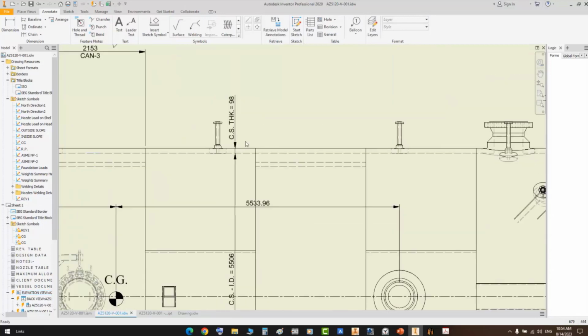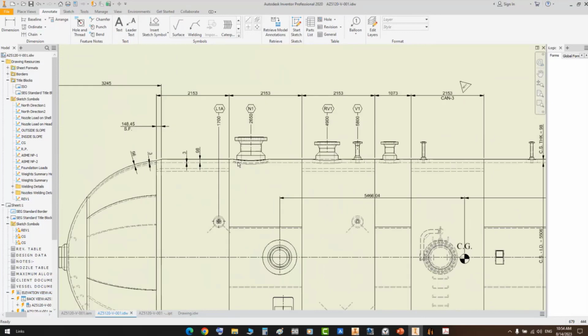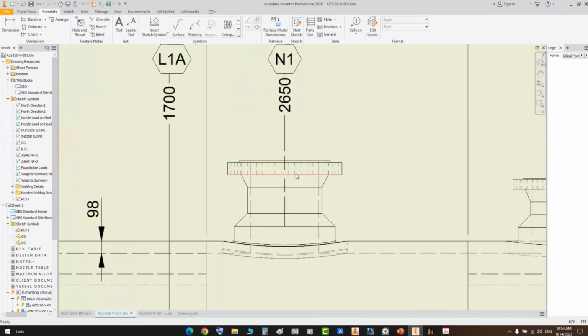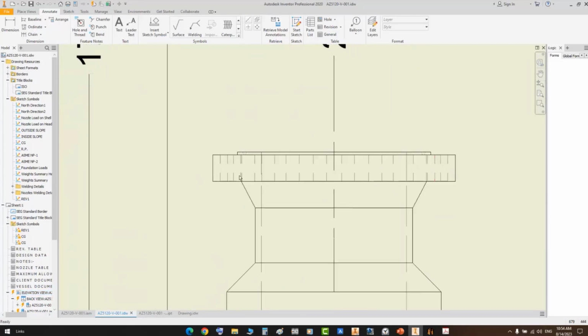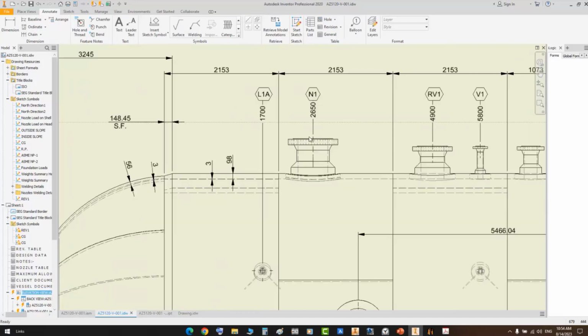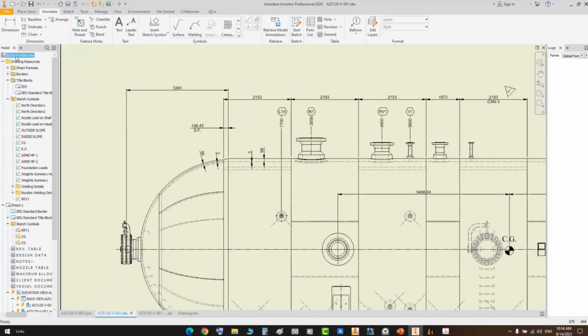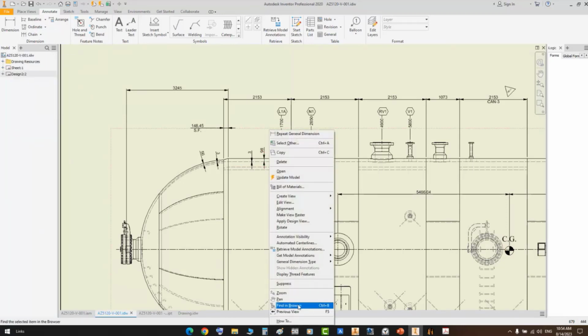Okay, that's fine. That's what I was looking for. One more thing I would like to indicate here. For example, for this flange, you may not want to add the hidden lines here. You can see that it's a huge number of lines, and I don't need it. So this item only you would like to make as a visible line only, not including any hidden lines. From the tree itself, if we collapse this tree, you can get this view from here.